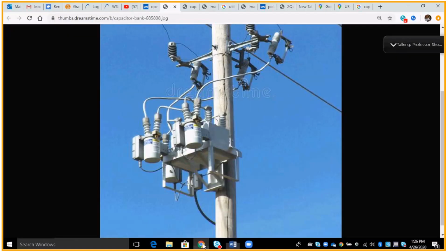And that's as simple as you've got this going to the capacitor unit. Let's take this protective cover off, take a jumper, and go from here to the pole ground. The case is also grounded. Just take a jumper from here and go to the case if you need to. After that has been done. All right. Remember, you're not doing this by hand. This all has to be done by sticks until every phase, every unit is completely grounded.